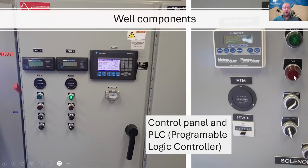There should definitely be some sort of alarm. So if your pump fails to start, it should trigger some sort of alarm. Something maybe that's just like a light outside of the pump house. Sometimes it can be connected to SCADA and it can like call you on a phone if that occurs. But it's so important to have some sort of alarm for a pump if it doesn't turn on.